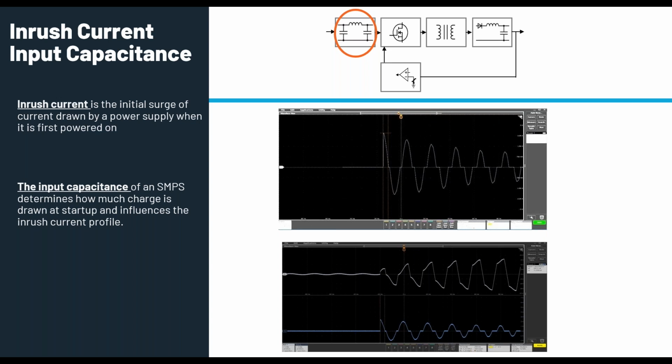So it's important to accurately measure the inrush current, add properly rated fuses and protection devices, and ensure the power supply reliability. It's again important to measure this current. We can do this measurement manually by placing cursors on the scope, and we also have an inbuilt measurement which will guide you through certain steps, capture the signal, and show how much the inrush current is.